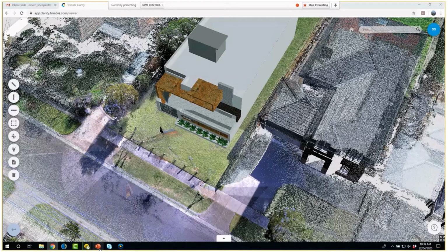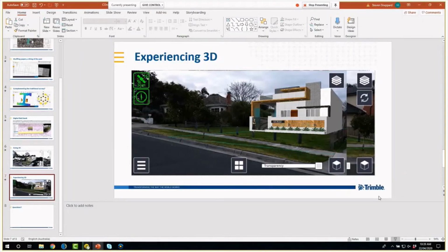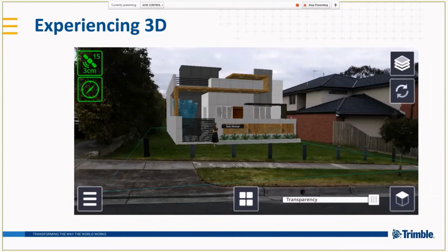So this is the same location, using Sight Vision to go out onto the site, have the 3D model placed and georeferenced where it should be in the world. In this case, this line work, I should have removed this, but it was at a 0. It was never at the correct elevation, so I'd roughly brought it up to where it should be visualized, but it does create a little bit of a parallax effect when it wasn't quite on the ground level.